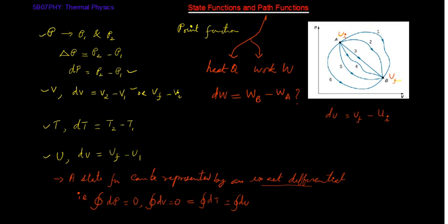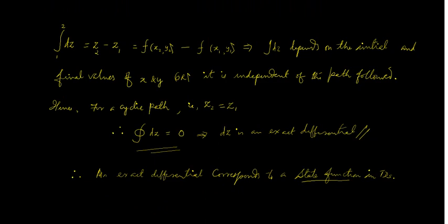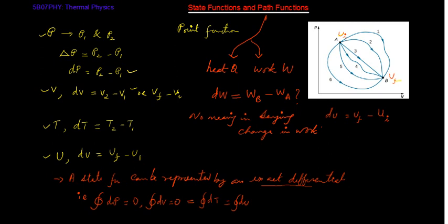So what is the meaning of dW? dW is not a small change in work. It cannot be called a change in work. This is very important: never use the phrase change in work, because change in work has no meaning.